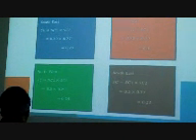And this is the calculation to find the shading coefficient, which is equal to SC1 times SC2. For the southeast, we got 0.23, southwest 0.24, northwest 0.24, and for the northeast is 0.23.